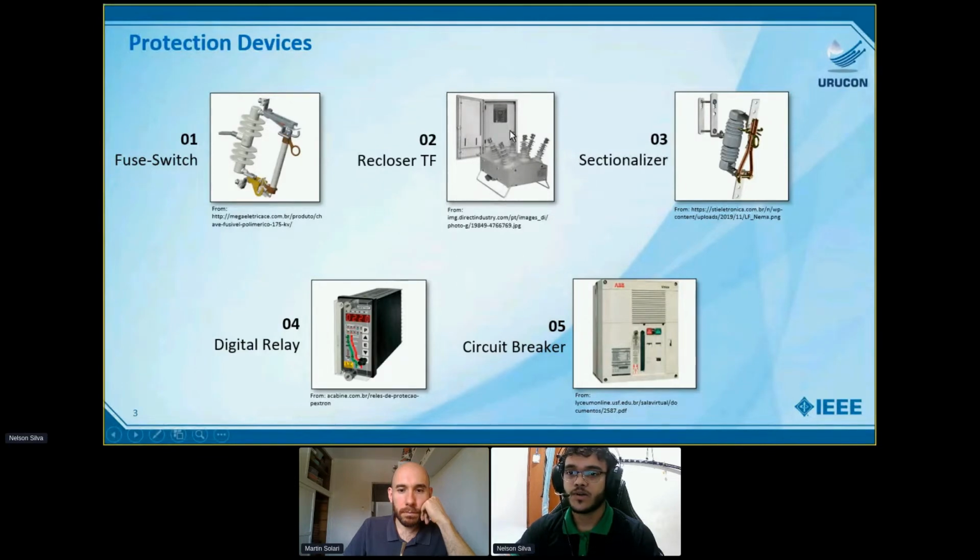The recloser restarts the system and protects it during faults like transient surges, and it has 4 operations, two fast and two slow. The section analyzer sections the system and helps with maneuvers. The digital relay is usually installed together with the circuit breaker with CTs, and it shuts down the network during overload or overcurrent too.